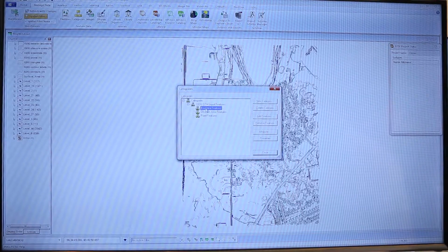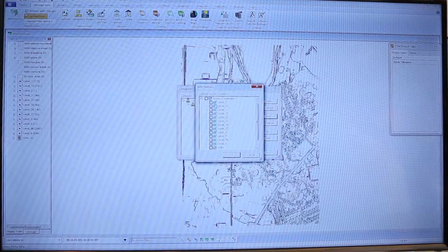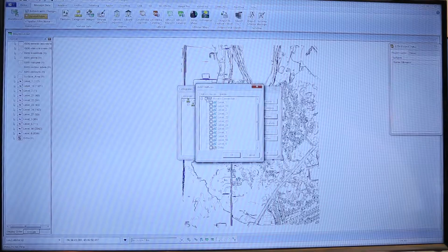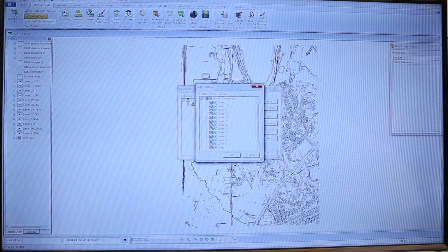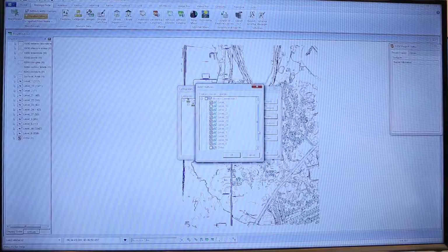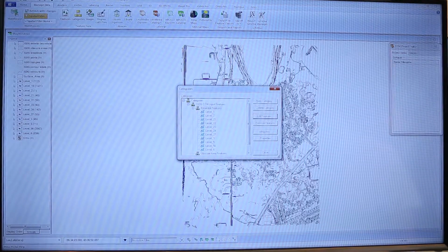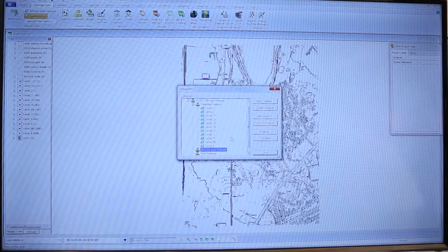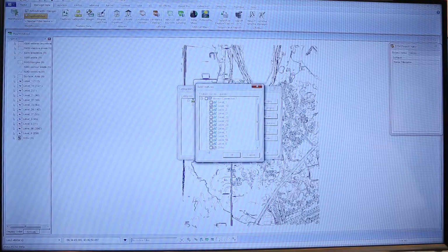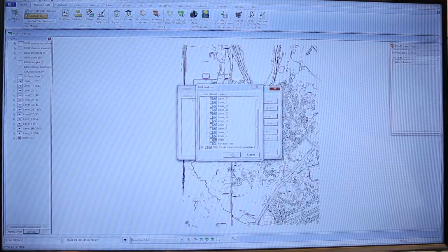So first, for our breakline features, I'll define the features that we'll use as breaklines in the elevation creation. So that's all of these except buildings, have a background ortho, and surface area. And for obscured area features, we're going to use our buildings and water bodies.